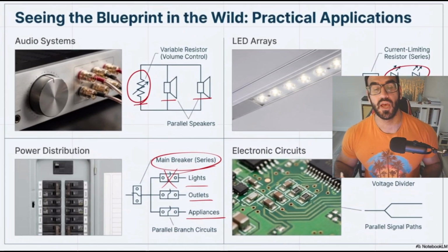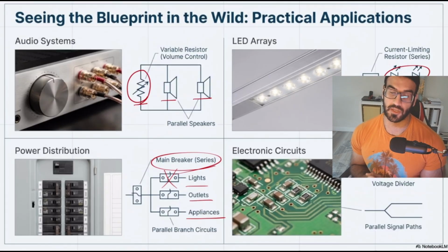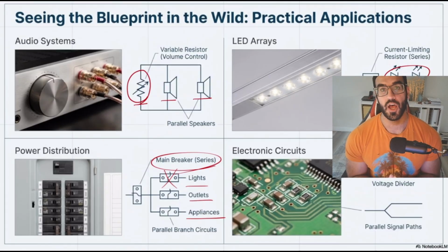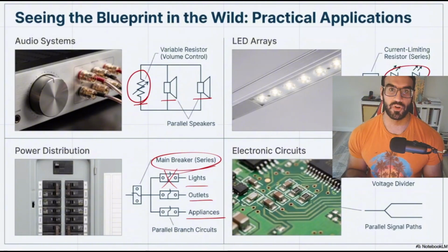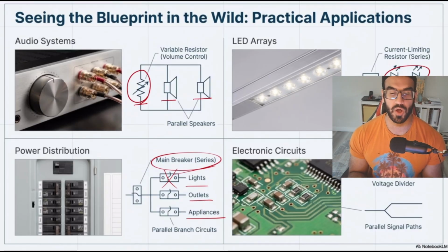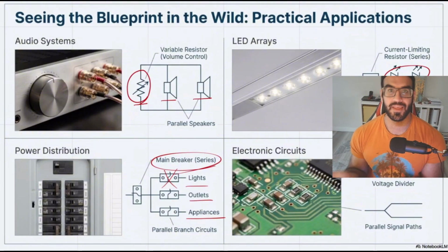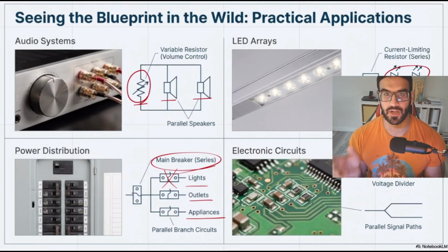So at this point, we were talking about the mixture of parallel and series circuits, which is very important, because as you just saw, it's common around the world that we are not only going to have one series or one parallel, we have a mixture of them. So it is very important to know the steps, to do it one by one, then apply all of those calculations, find the main things, which are R total and I total, then move backward to find your smallest currents and voltages.